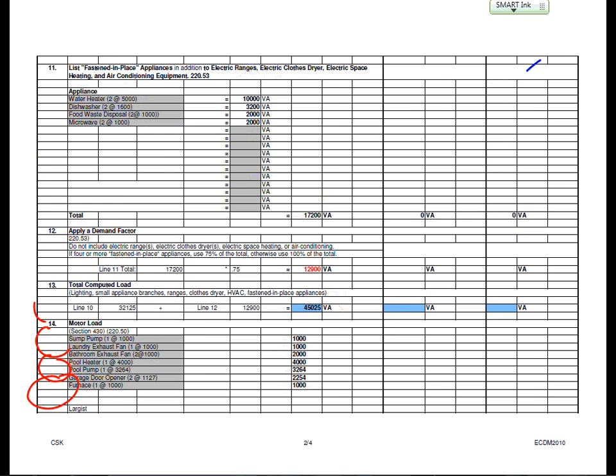so what we did, Karen, is we accounted for the lighting load and the receptacle lighting load, for the kitchen receptacles, small appliances, for the laundry, for the heating, for the cooling, heating and cooling, we choose the largest. We accommodated also for the ranges and the dryers, right? What else is left in the apartment that we need to pay attention to? What else is left based on the NEC code book?